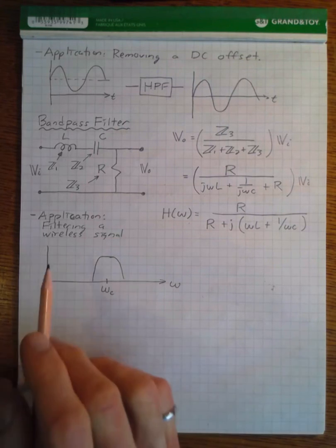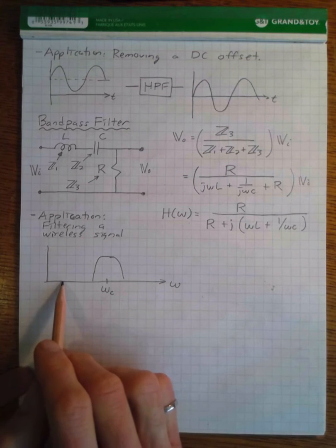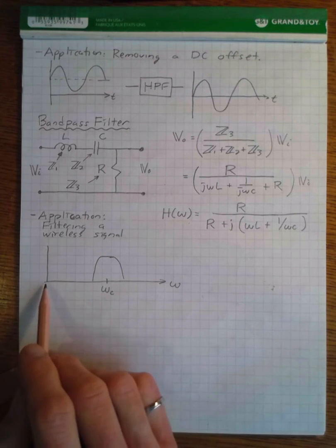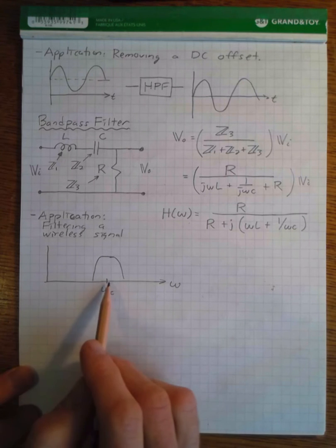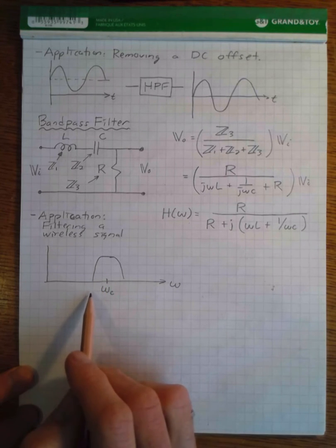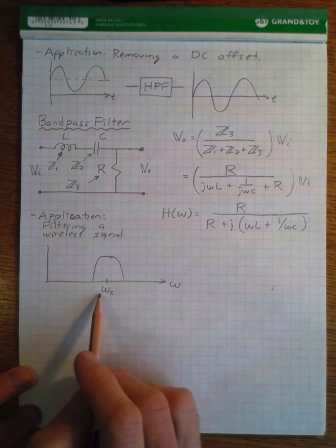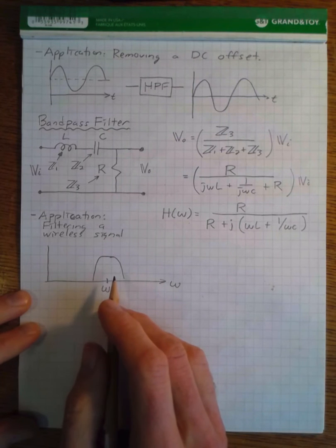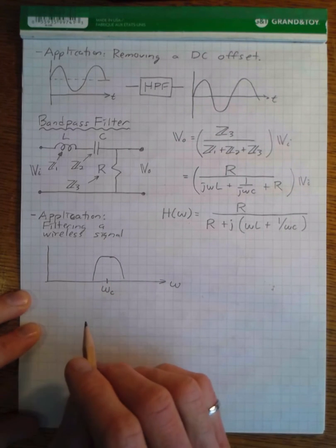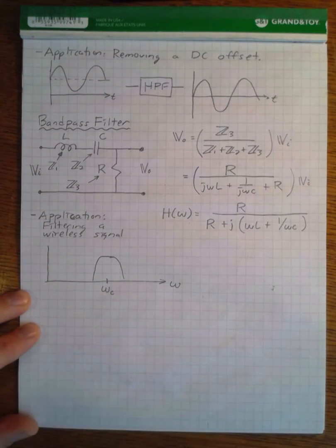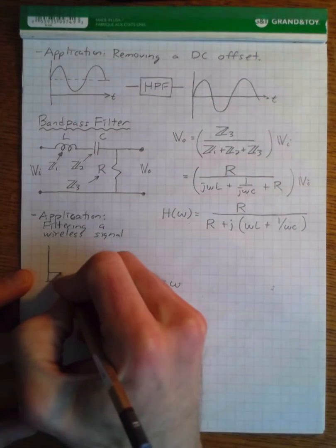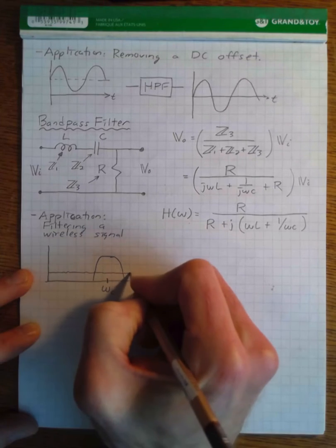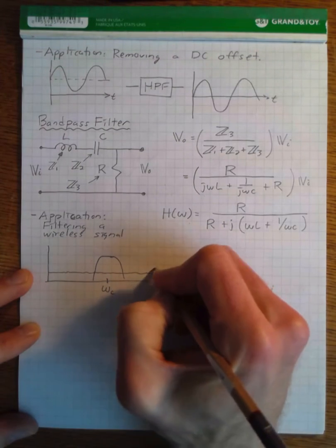And so we'll take a low frequency signal, multiply it by a sinusoid, which shifts it up into the high frequency. And so if we took a frequency domain snapshot of a wireless signal flying through the air, it would look something like this. And so similar to the audio example that I had when we were talking about the low-pass filter, wireless signals are also subject to a very broadband noise.